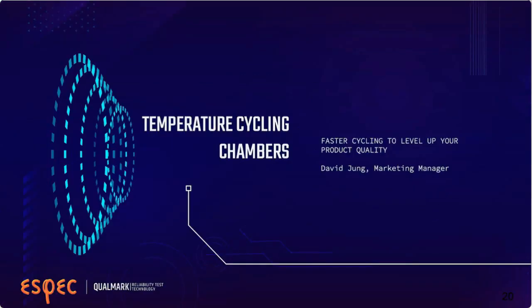Hello, this is David Young again. I wanted to cover some more information about temperature cycling and the equipment used and what it requires. As Neil said, thermal stress means using fast ramp rates and greater thermal ranges to stimulate your product's failure modes. Your situation may not allow you to embrace the full HALT attack with destruction as your goal. So you might just be screening for defective parts or defective manufacturing. That might be more in line with your needs.